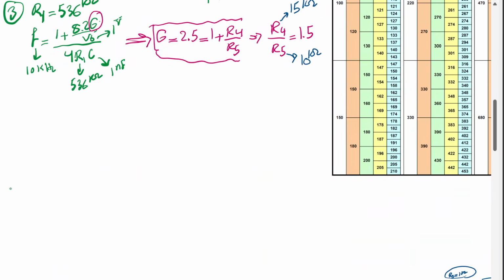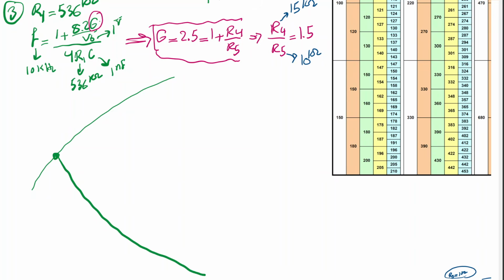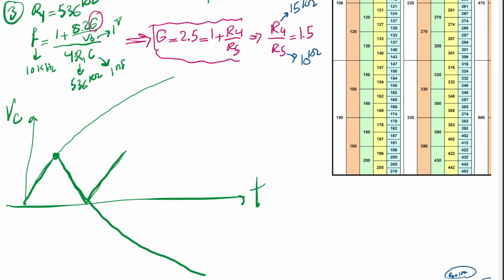I'm going to show here. So the cap, as I said, we focus on the linear portion of the rise, and then we got to this point. And then at this point, we are now discharging the cap again using an exponential drop, but sticking with the linear portion of the exponential drop. And remember, this is the voltage of the capacitor, and this is time. So we have now using this region, and after that we go back to the linear region, and this is the way we generate the triangular waveform at the output of the circuit.